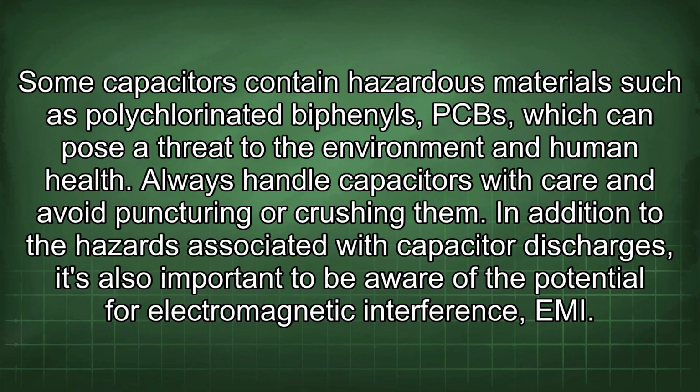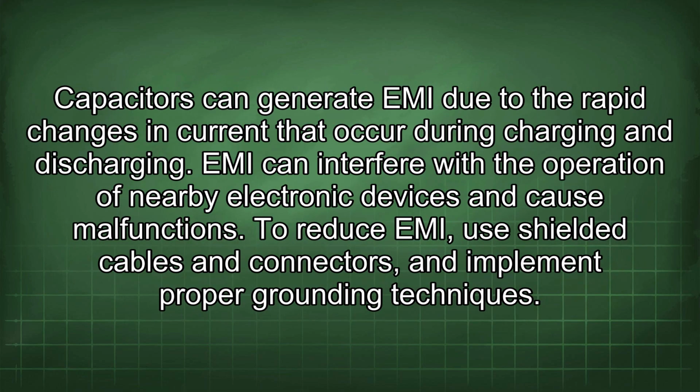In addition to the hazards associated with capacitor discharges, it's also important to be aware of the potential for electromagnetic interference, EMI. Capacitors can generate EMI due to the rapid changes in current that occur during charging and discharging. EMI can interfere with the operation of nearby electronic devices and cause malfunctions. To reduce EMI, use shielded cables and connectors, and implement proper grounding techniques.